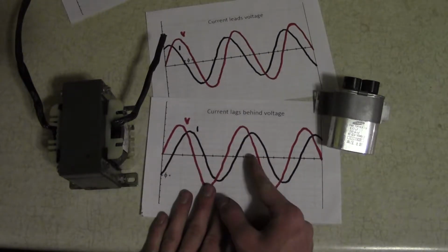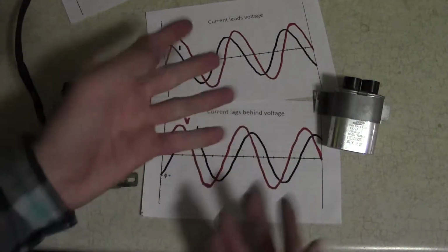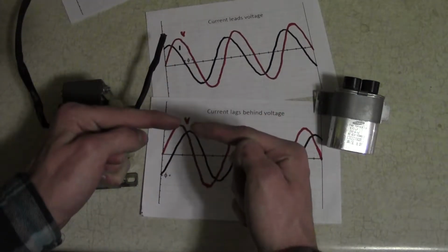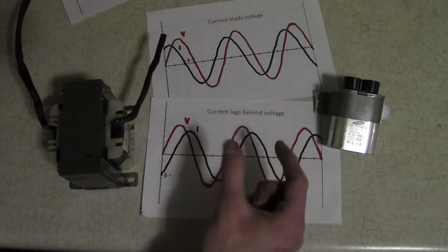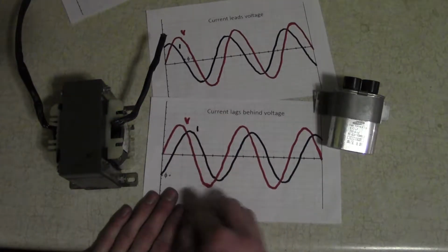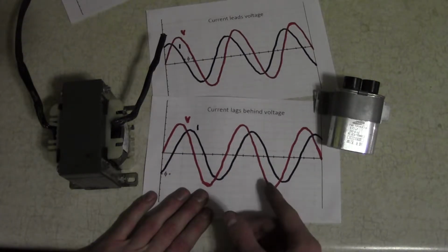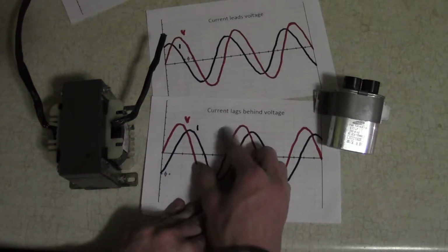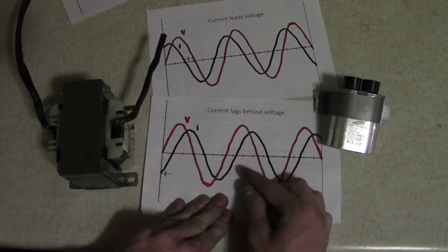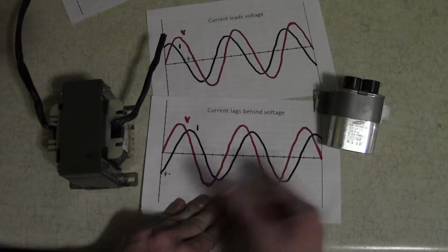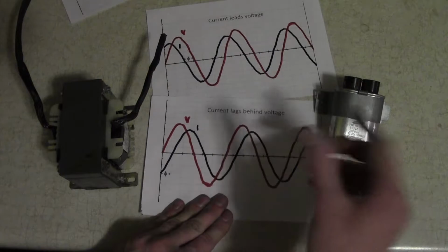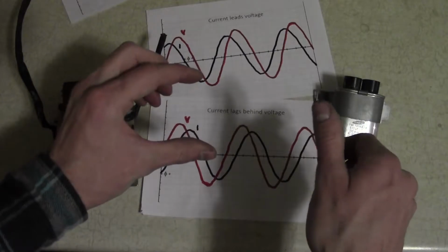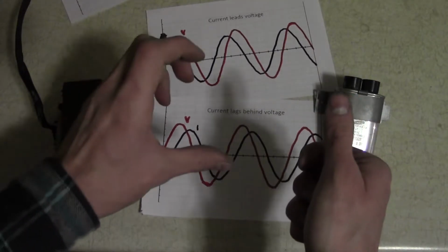Now, how will I know when these are in line or if these are out of line? Well, I'll simply have a digital meter on my truck. It'll tell me the voltage, the amperage, and the power factor. It'll just be a number. It'll have this symbol that I showed you, and then it'll have a number between 0 and 1. So if the number is 0.95, say, I probably will not bother fiddling with the power factor. But if I get a number on that power factor meter that is exceptionally low, maybe like 0.7, 0.6, something like that, I will adjust my knob, and I'll simply turn the knob up, and the number will increase. And I'll just keep turning up the knob until I get to about 0.99, and then I'll leave it.